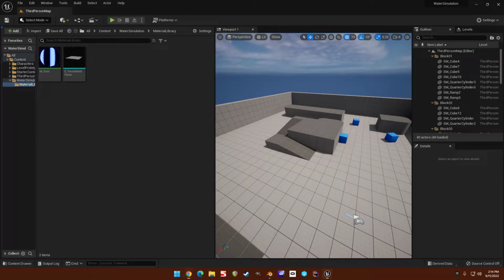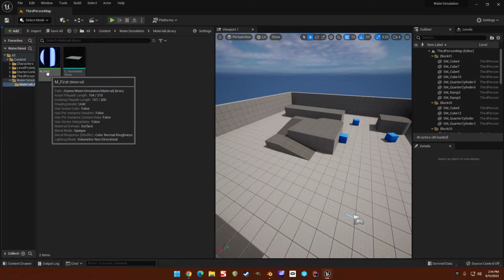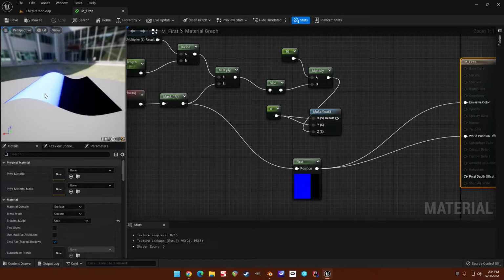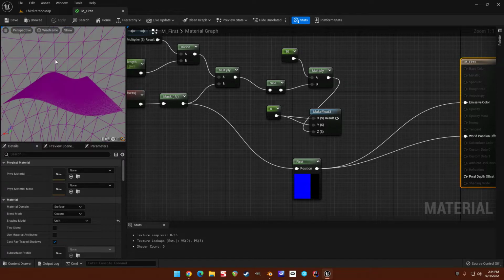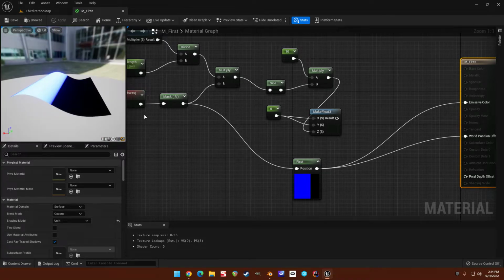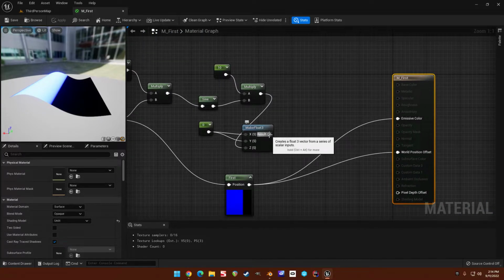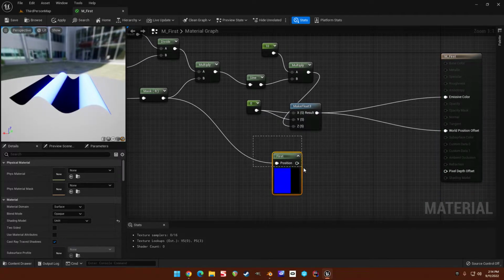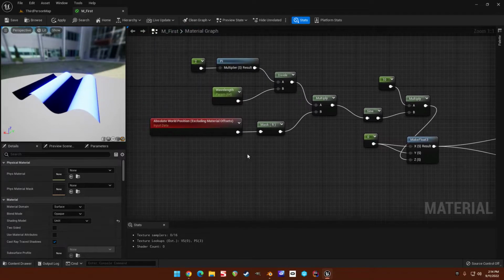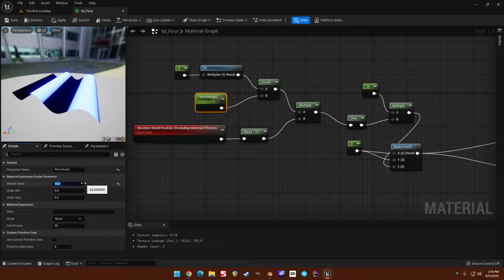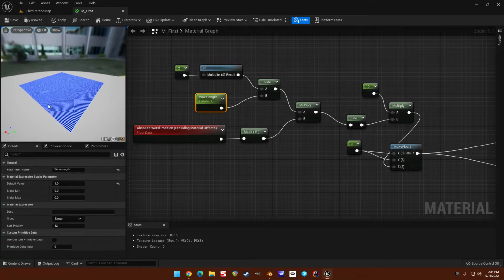So we've done that. Oh, I wanted to mention something, which is the Nyquist frequency. So if you think about this plane and how it's been tessellated, right? There is a limit at what wavelength can be represented on these vertices, right? So let me hook this back up so that we can see this better. I'll just kill this for now. And so what would that be, right? If you remember, we cut it down to 1 centimeter. So can it represent a 1 centimeter wavelength? The answer would be no, right?